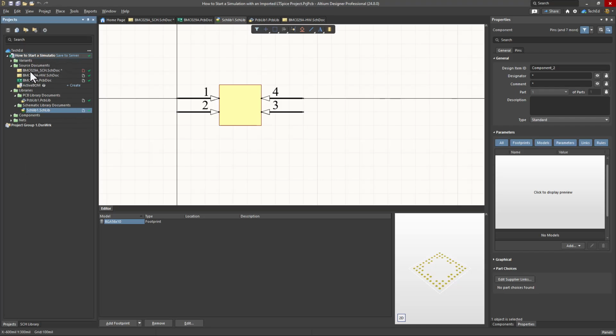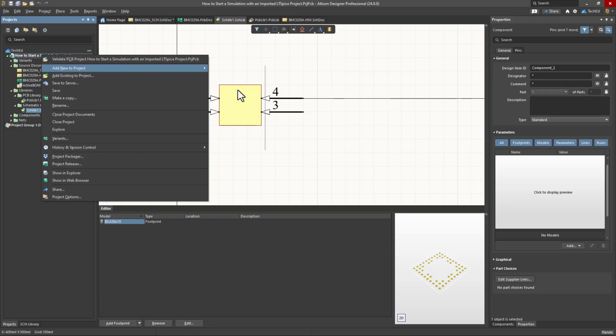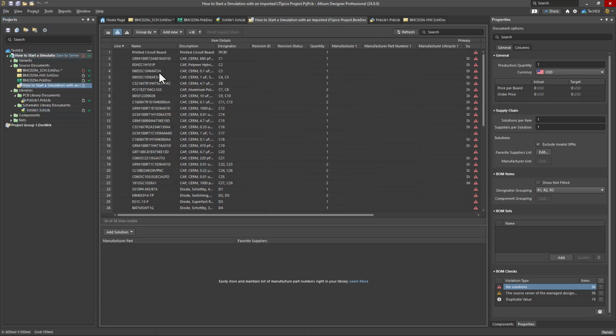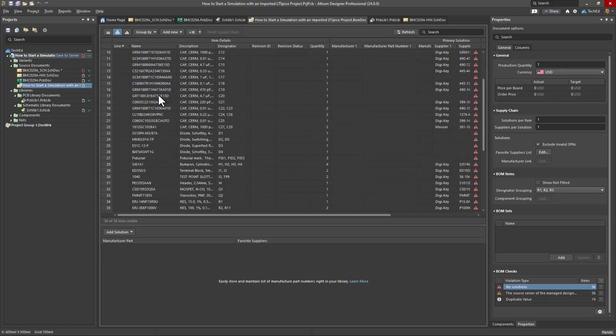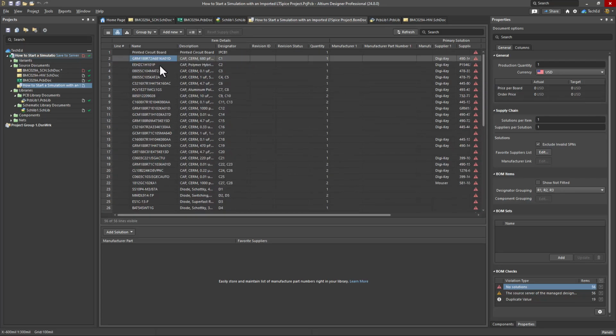Moving on. Next in our project, we have this thing called a bill of materials. You can right click and add a new active BOM to Altium. Now here's the thing, a bill of materials really is a list of materials, like components that you would include in your design, your schematic, your PCB, whatever. But active BOM is a schematic spreadsheet with real world data. Okay, so it has your printed circuit board as part of the components you need to buy. Pretty much this is your buy list to make this entire project possible.